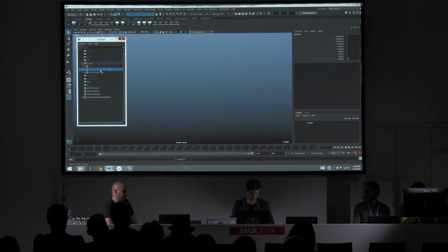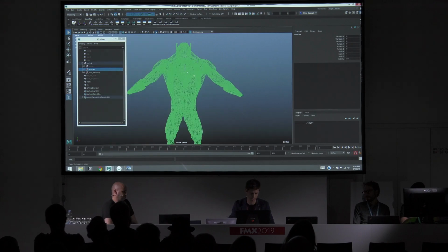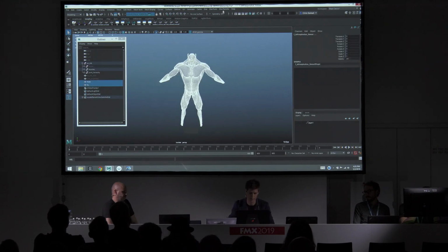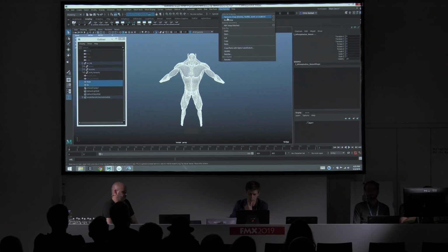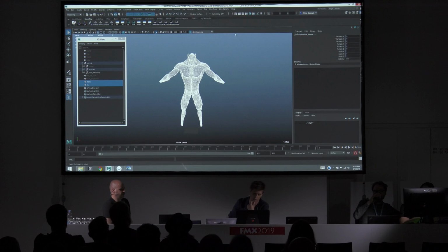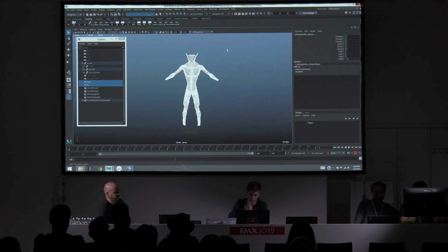So we'll do the same thing again. So I'll select the source mesh, the target mesh, and everything I want to warp. And then in the Ziva transfer menu, I'll come down to this time. I'm going to use harmonic warp. And then the tet size is already 2. I'll hit warp. And then wait for a second or 2, and it's done.